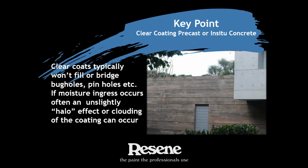So just as I mentioned there, with clear coating Insitu concrete or Precast concrete, it makes us a little bit nervous at times. And the issue that we have is that if you have bug holes or pinholes or texture, particularly on the picture that we've got there with a timber board profile or pattern on a surface, it looks fantastic, but often there can be voids in the surface, and clear coats don't necessarily bridge or fill a lot of those holes that are there.